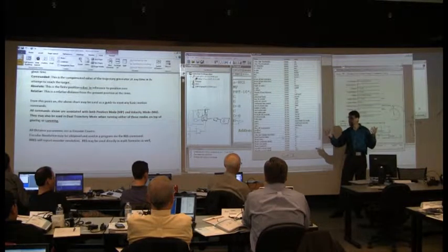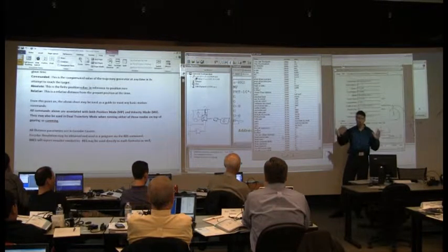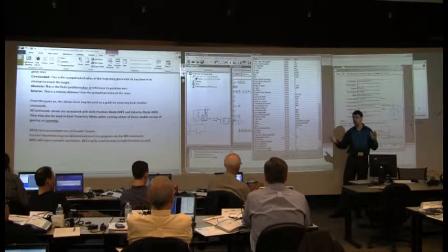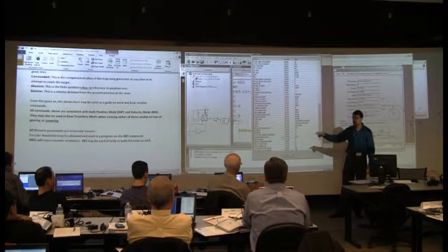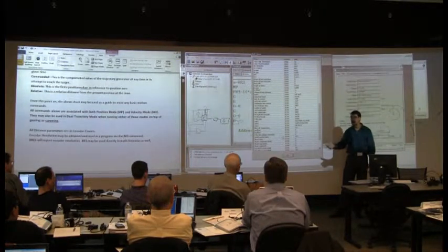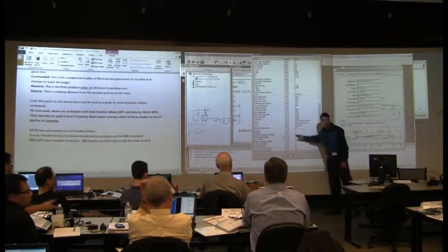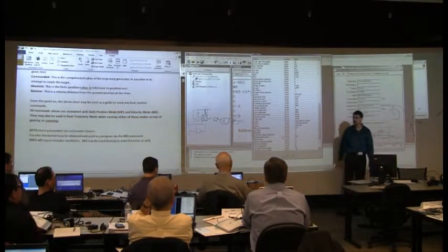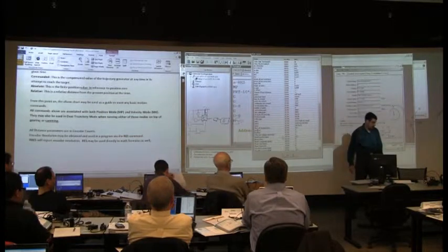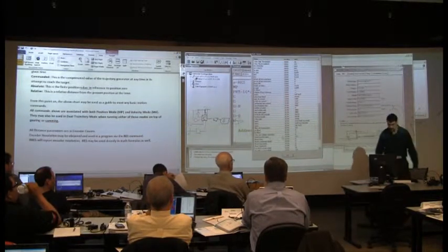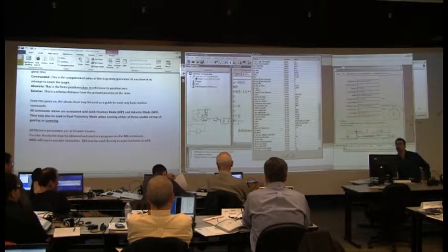There's some inductance in there. There may be some other parasitic resistance. But the bottom line is, the slower you're going, the higher the current's going to be in those windings on a continuous range, because there's no back EMF to suppress it. So we have to put in a low bus voltage threshold to prevent excessive currents. So that's another limit you may need to be aware of, and that's hardware.